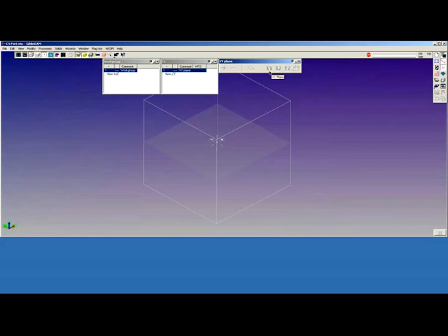Primary planes are designated as XY, XZ, and YZ. When you deviate from a primary plane, we'll replace or substitute one of the call letters for an H, a V, or a D. HVD represents horizontal, vertical, and depth. Depending on how the orientation of the coordinate system is defined, one of the axes can be substituted for a V, a D, or an H. The toggle depth icon, this tile here, reverses the polarity of a coordinate system.